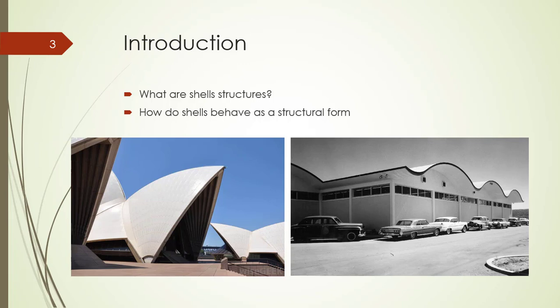A thin shell is defined as a shell with a thickness which is small compared to its other dimensions, and in which deformations are not large compared to thickness. A primary difference between a shell structure and a plate structure is that in the unstressed state, the shell structure has curvature as opposed to the plate structure which is flat. Thin shells are an example of strength through form as opposed to strength through mass.